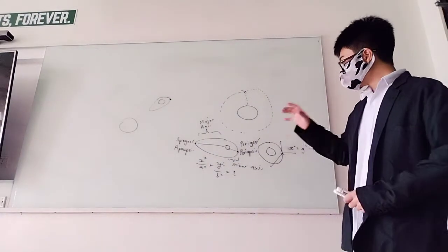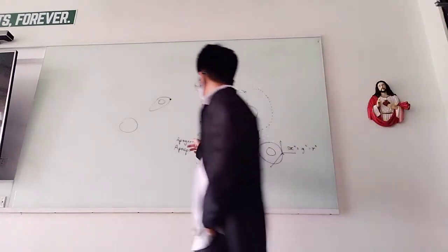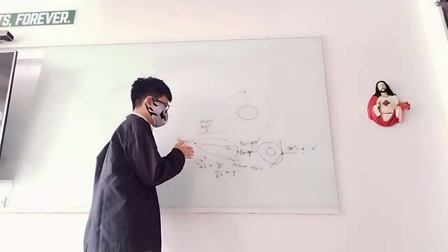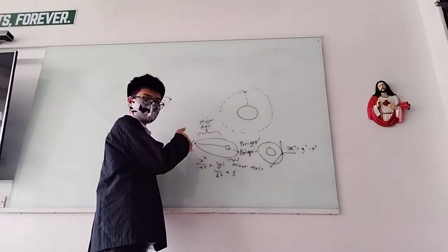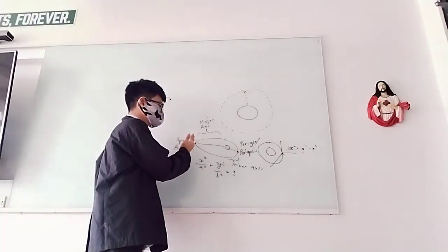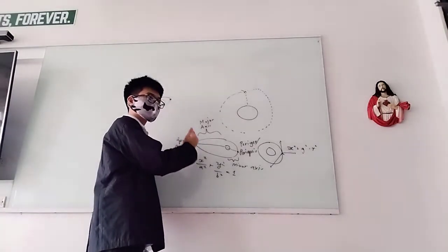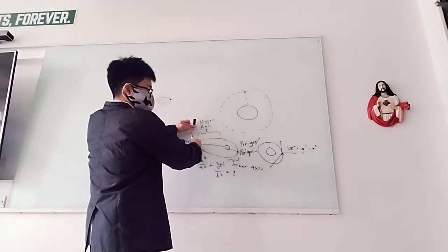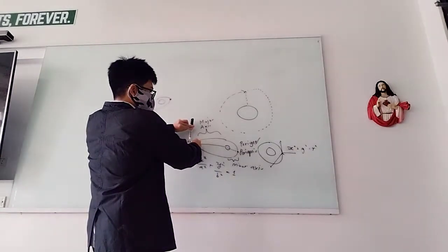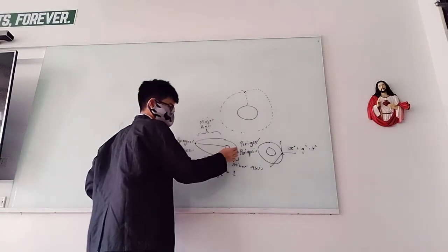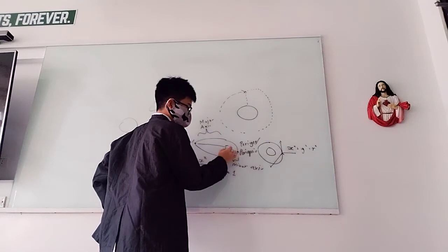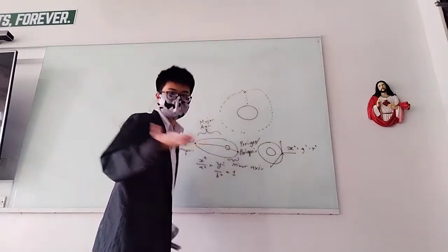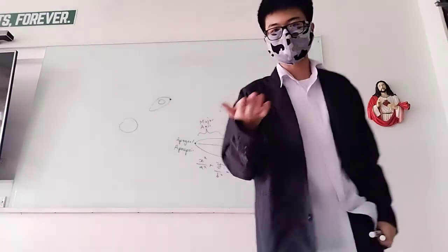In the opposite case, if you're at your apogee and you burn directly away from the direction you're going, so say your vector is here and you burn upwards, that means you're losing velocity, and your periapsis or perigee will shrink, and eventually you'll be on a collision course towards your planet, which is not good.